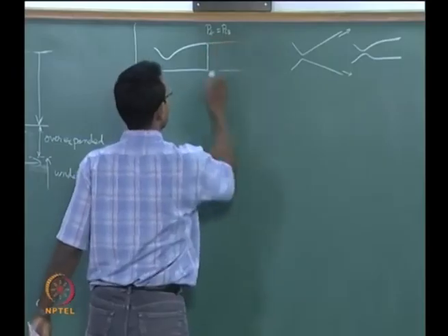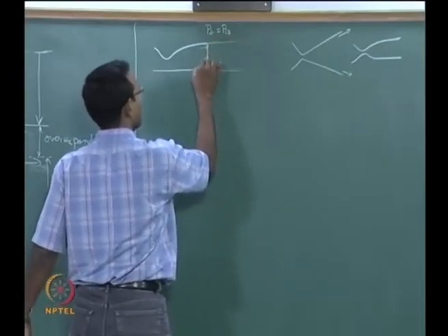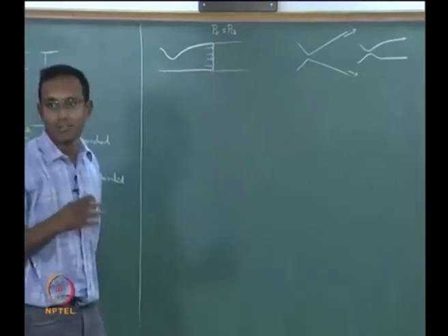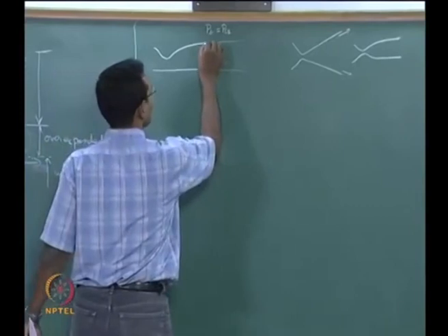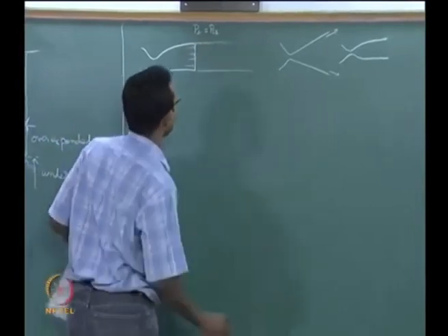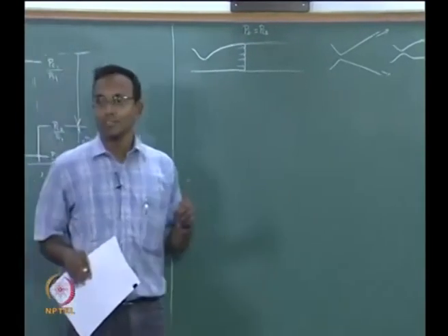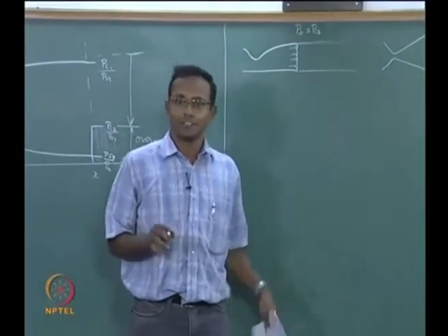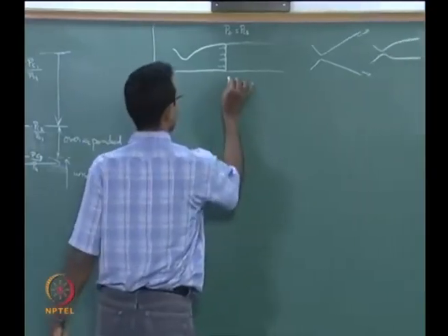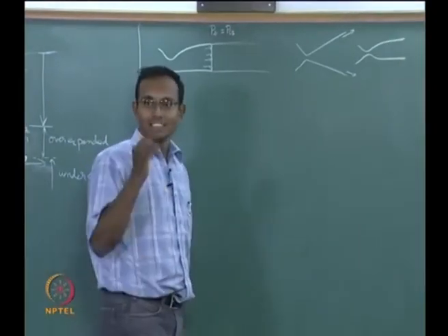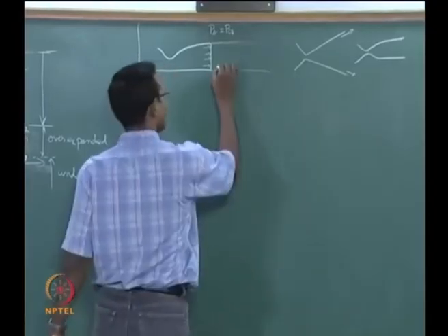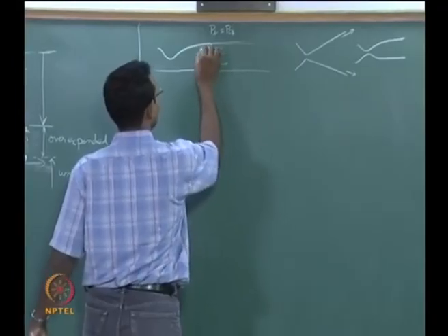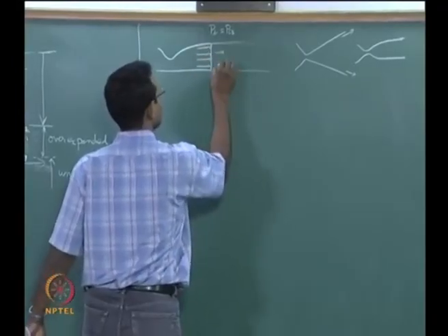So, my jet is going to be just parallel to whatever is incoming, except that before the shock it is supersonic and after the shock it is subsonic, with exactly the same mass flow rate, and so it just goes out as a straight jet. And we assumed one more special thing, we are in inviscid gas dynamics. So, there is outside air and it is stationary, and this gas is going with some reasonably high velocity. I have to draw arrows such that these are longer and these are shorter.